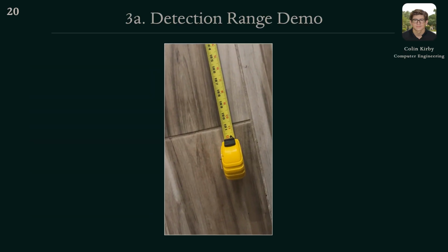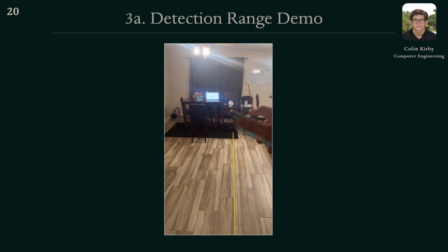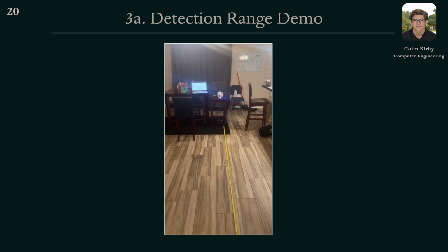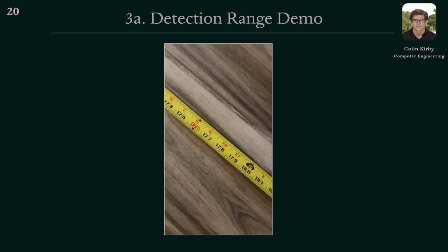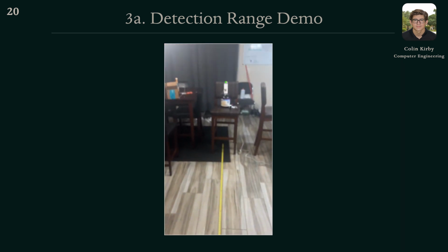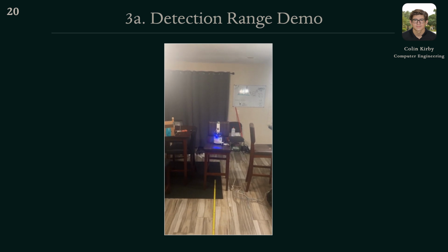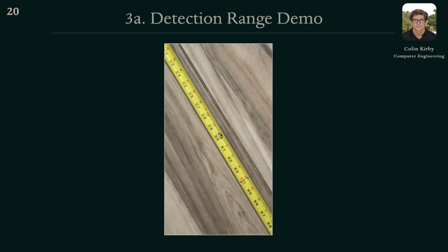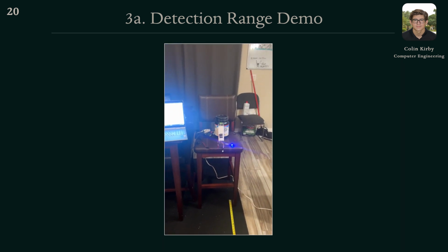We're going to start at 16 feet and move forward, and whenever the blue LED on the device down there triggers, then we know that a person was detected. So we're going to go with that. Okay, there we go. Take that step forward. That's like, let's say 15 feet, honestly. All right, so we're testing from 10 feet here. Just to see, let's make some motion, wave our arms. Here we go. So this is the test one at 5 feet. I don't want to move too much because it's going to trigger, but then we start making motion, and there we go.